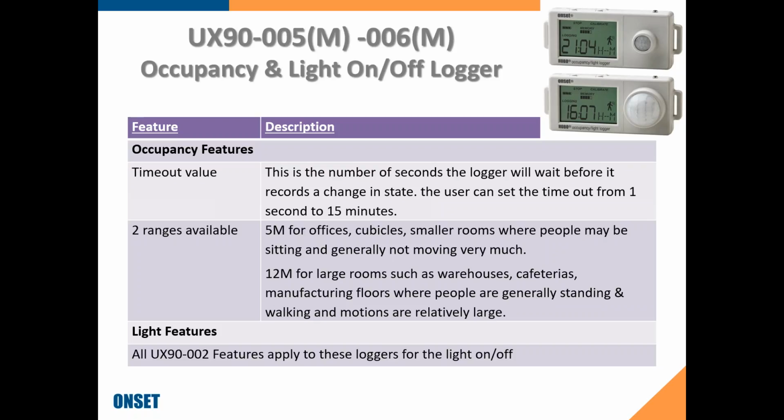Especially also, this will work in another application. Let's say you do have occupancy controls within a room, and you're trying to tweak them. A lot of these different occupancy controls in the marketplace have a delay built into them that is controllable by the end user. And they usually come through with a 10 to 15-minute delay built into them. So somebody walks into the room, the lights turn on, and then they walk right out of the room 20 seconds later. Those lights are on for 15 more minutes. So you can actually tweak those to shut off sooner than 15 minutes. So it's a great way to become more efficient again after the fact.